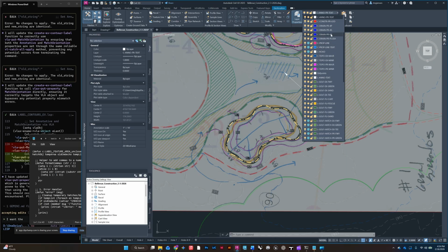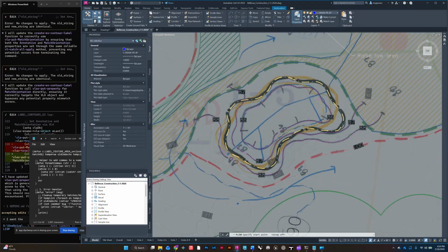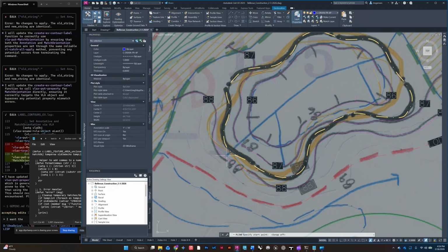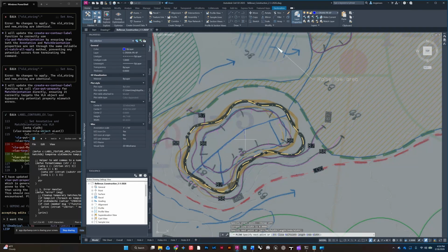So go to C, drain, PR, perforated, and you're going to start at the top of the bunker, the highest point of the bunker, and draw this pipe in as few jagged pieces as you can. Really, you're only changing the direction of the pipe when we do major directional changes.